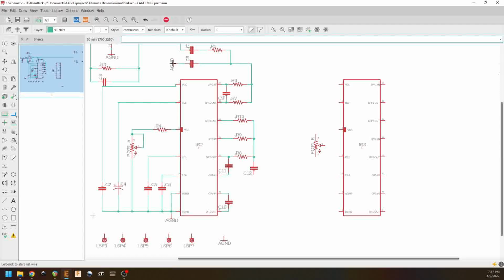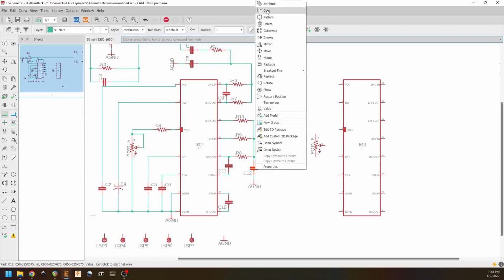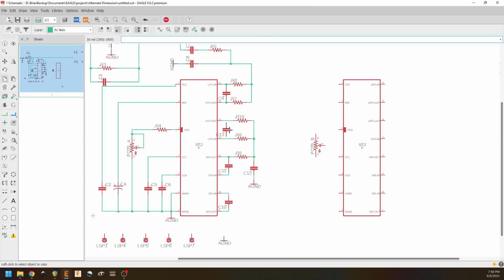And we need our capacitor here to go to ground. And we also need a capacitor between these two pins, for the sake of our filtering. And now our output comes off of pin 14, because this is the output of our multi-feedback filter arrangement.